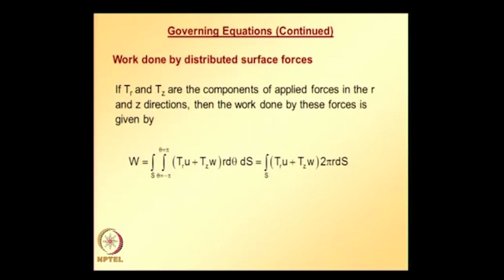Again, since this is an axisymmetric problem, we can integrate with respect to theta going from minus pi to pi, and then this integral of work done by the distributed surface forces reduces to a line integral. So, potential energy functional is given by strain energy minus work done by the applied forces. Strain energy is basically an area integral.